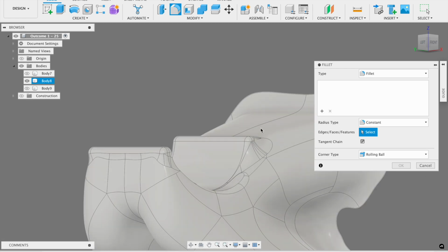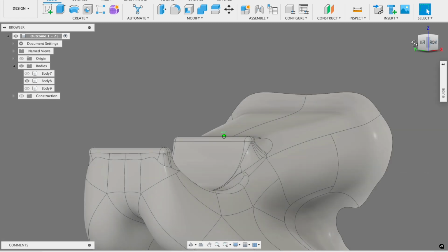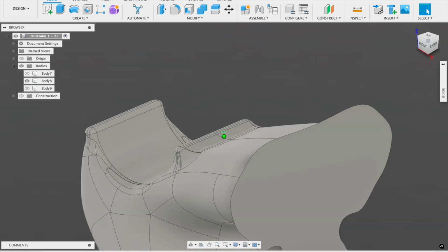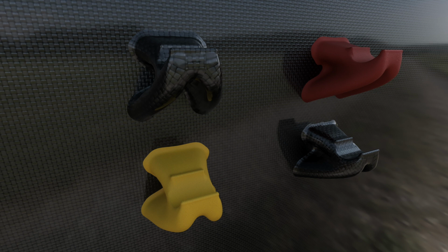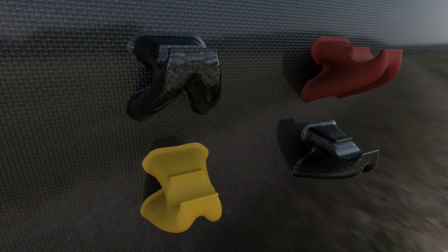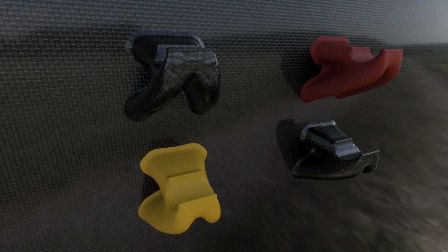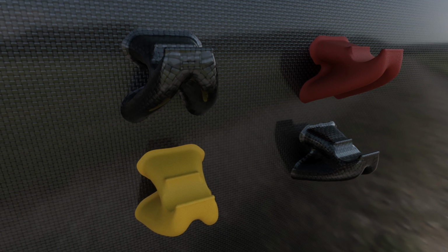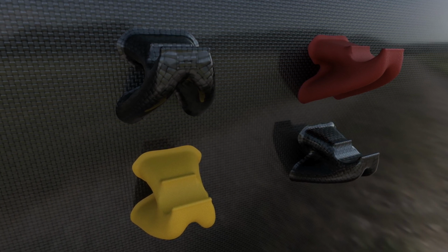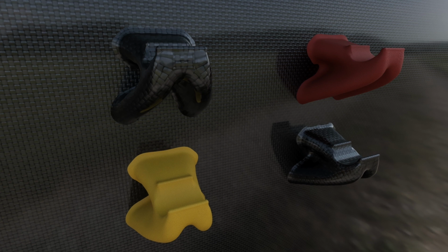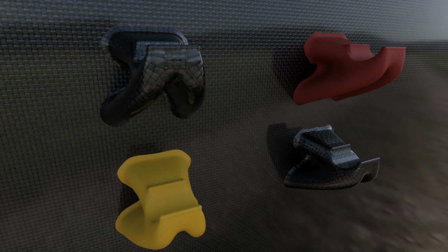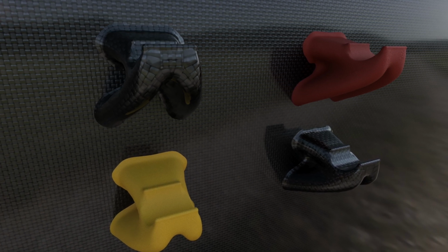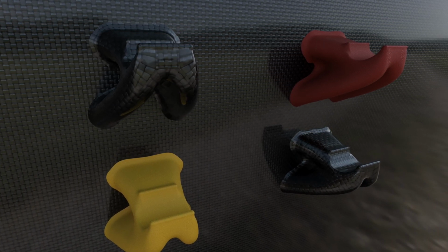It doesn't need too much modeling to make the design actually happen. There's only 3 relatively simple bodies involved in doing this. The harder part is understanding the preserve and the obstacle, and it might not be entirely intuitive that you need to make the void geometry rather large to compensate for all the space you need to then place the object on the actual hook itself, as well as how to put the load cases to get the outcome you want.